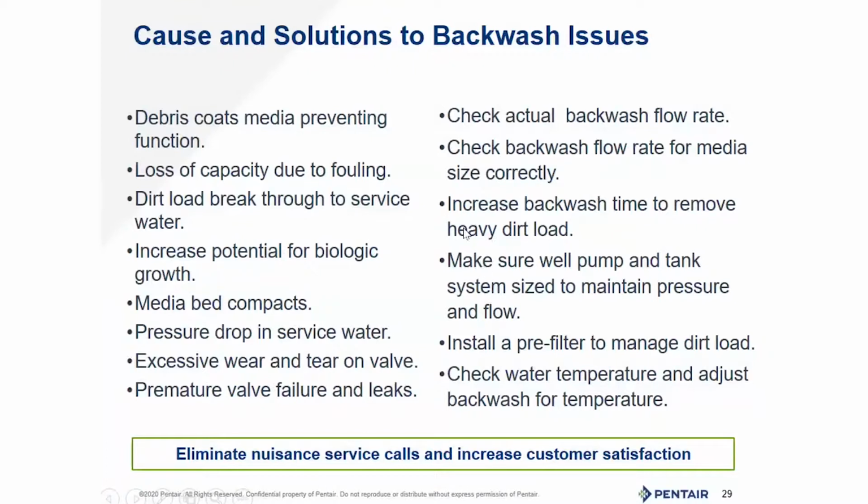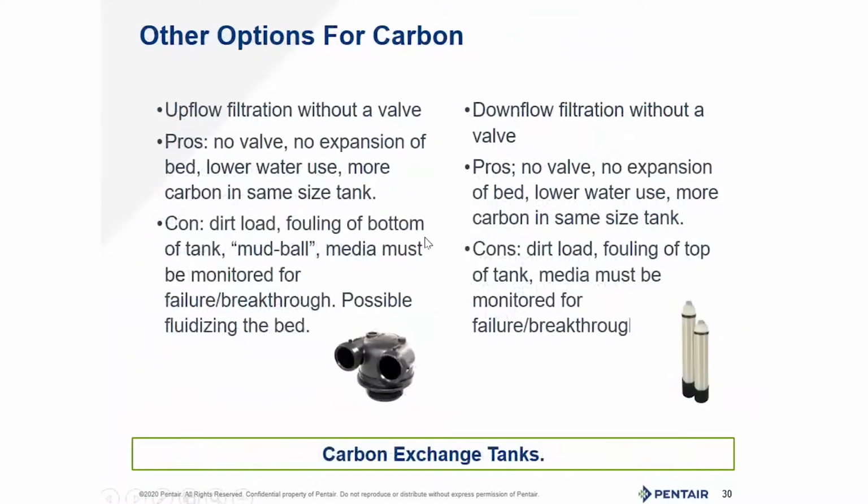Some of that's increasing backwash time. Sometimes it's just using a backwashing filter versus like an exchange tank scenario. And then water temperature and pressure impacts. And another thing that is optional for a backwashing filter, especially if you're concerned about organics or its specific application, warm water backwashes. We'll get into it in a moment. But there's other options for carbon.